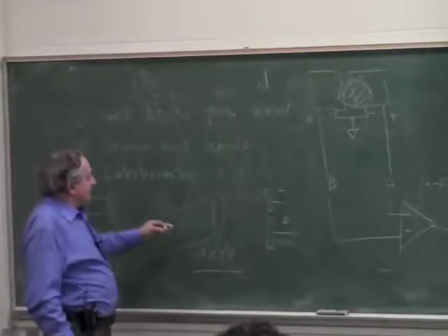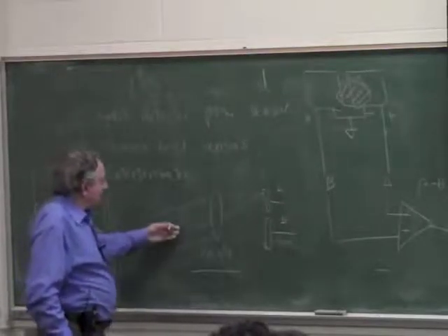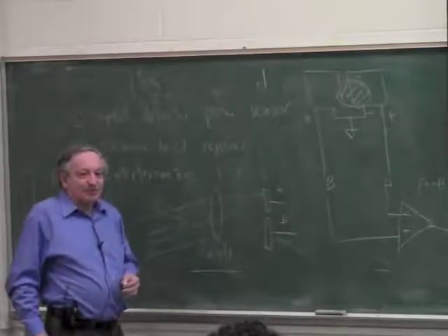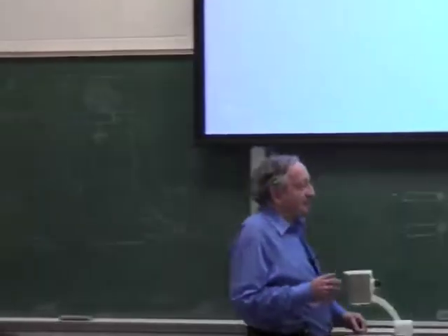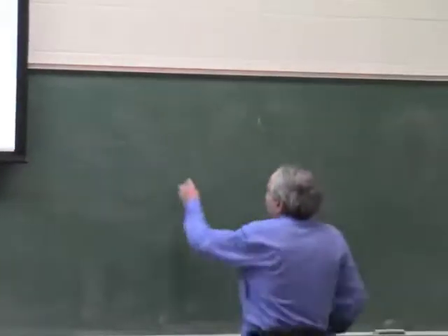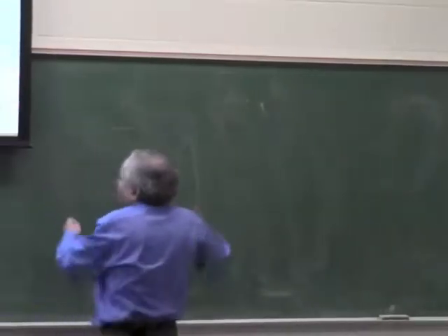In this case, you have to design it correctly so that the lens is large enough that it will capture the whole beam. So it doesn't have to be a collimated source. For example, if I want to make an angle sensor with an LED, which is not a collimated source, I can do it as well. I can keep the LED at a large enough distance that it acts nearly collimated, or I'm sure I can come up with other configurations.